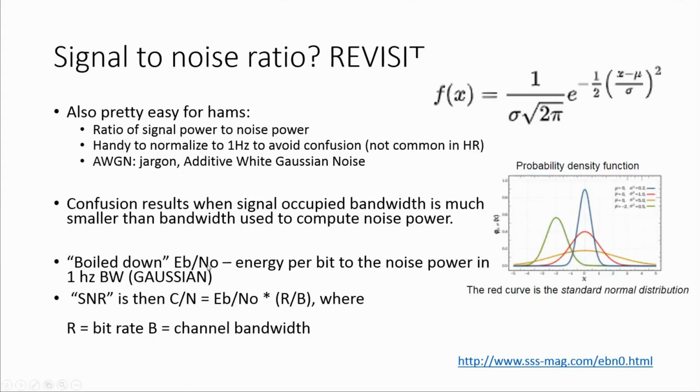This noise is referred to as AWGN, additive white Gaussian noise. Basically what it means is this frequency spectrum is flat, and the probability distribution, which is kind of a fancy word, is just what is the probability of a particular value around a mean occurring. So this equation is the Gaussian normal. And what's interesting about this is that it's a square in the exponent, which means it's symmetric about the origin, which is the mean value, and the spread is proportional to this sigma.